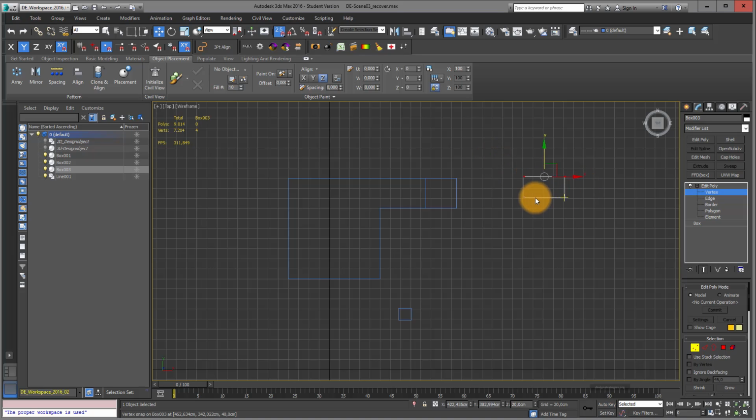I choose my vertex points and adjust them to the dimensions of a wall, a reference object, or whatever. So a box is quite often the initial starting point, and I draw it without caring about the dimensions, because with an Edit Poly on top, I can adjust it precisely however I want.